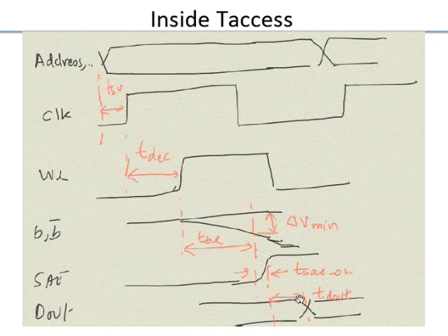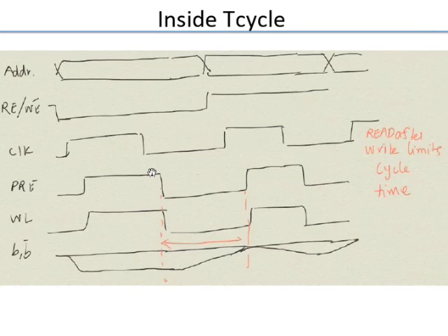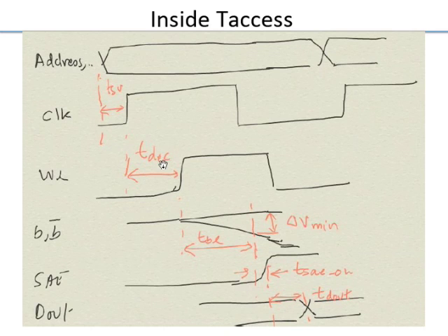Now we'll look at the decoder in the next class, not in this class: what you can do to reduce the decoder delay. Decoder is completely combinational logic. It's basically regular CMOS logic, and we have already seen techniques for reducing delay for logic gates, right? Essentially, you size things so that minimum delay is when you have equal efforts and so on. Now, in addition, you can do some more things beyond that, and we'll discuss that when we discuss the decoder. We'll here focus on the bit line time.